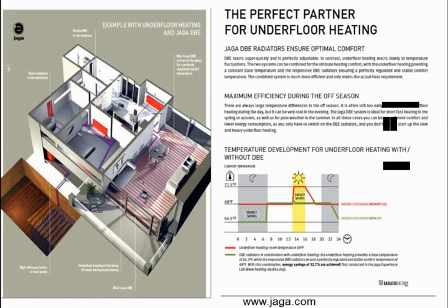That's right. And they've developed a low temperature radiator system, which can be used to supplement a radiant floor system. So now you can run the radiators on the same temperature that you're sending out to the radiant slab zone. So that makes it pretty nice for zoning and for combining the two systems together. That I thought was a nice little cutaway of what they're explaining here. You can see on the right side, you can see the radiant floor slab and how they've got the radiators in these various rooms for supplemental heat or for the shoulder season heat emitters.